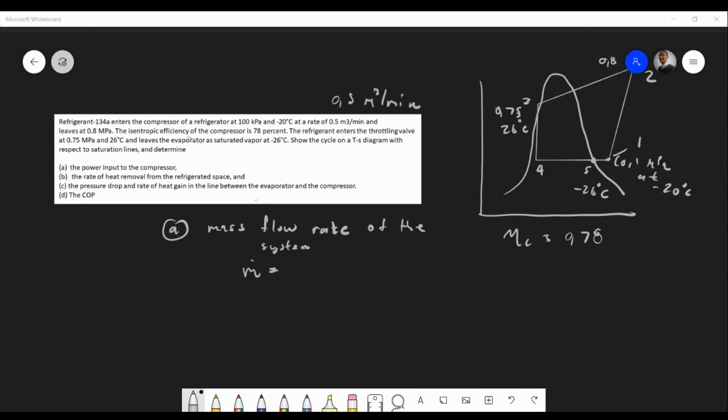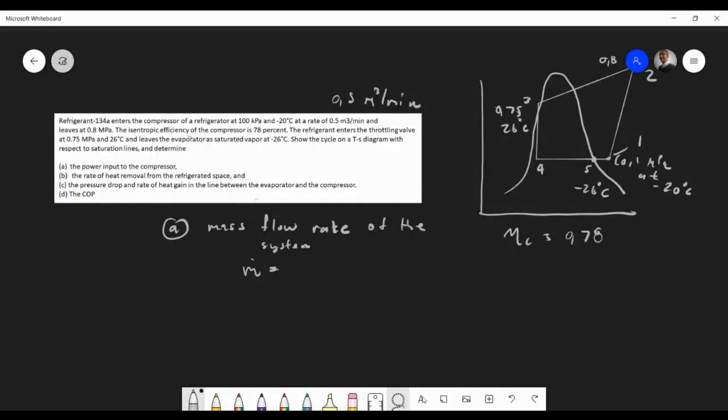Yes, velocity of a volume. Yeah, in fluid mechanics it was area times velocity of the fluid. Isn't that the flow rate? Yes. And then you multiply by density. Beautiful, that's what I'm looking for. So it's rho times your volumetric flow rate, or we can write it as rho V. It depends on how you want to have it.